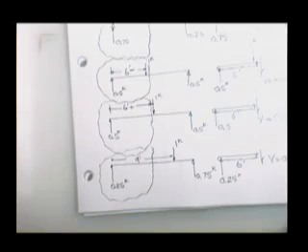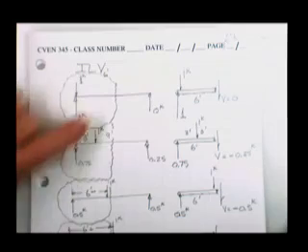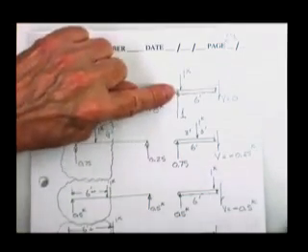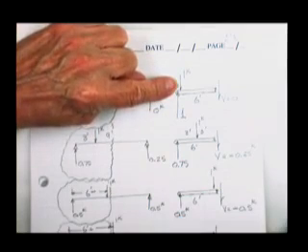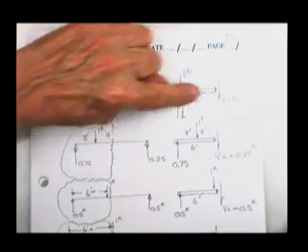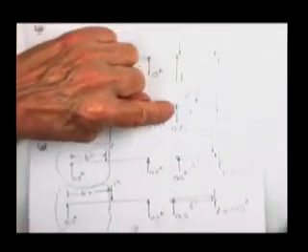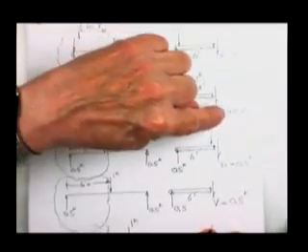Now then, I have moved the load across the beam, and I know how it influences the shear at the cut, at the point of interest. When the unit load is here, it causes no shear. When it's moved, it causes minus 0.25.